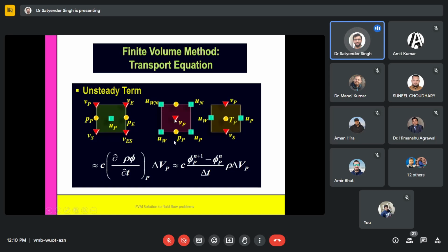Similarly for the v variable, we are getting unknown u in the advection term, so we will be getting an updated value of this one and pressure. And similarly for temperature, if you have to solve the energy equation as well in conjunction with the momentum equation, then the values coming from the momentum equation will be given to the advection term of the energy equation to solve, like say u del T by del x plus v del T by del y.